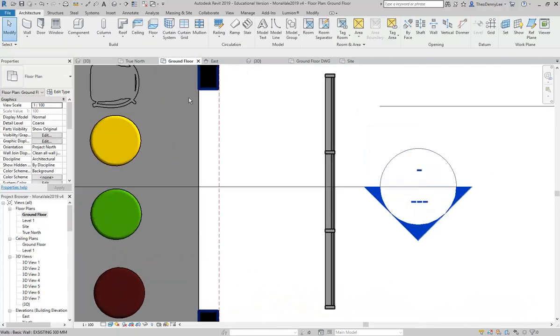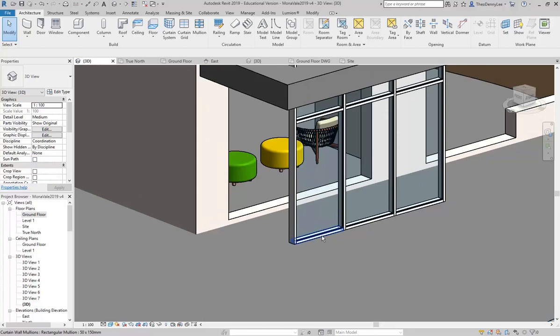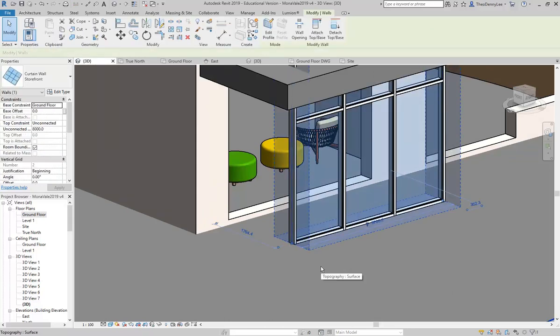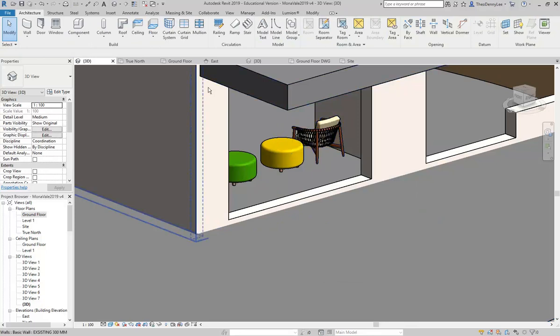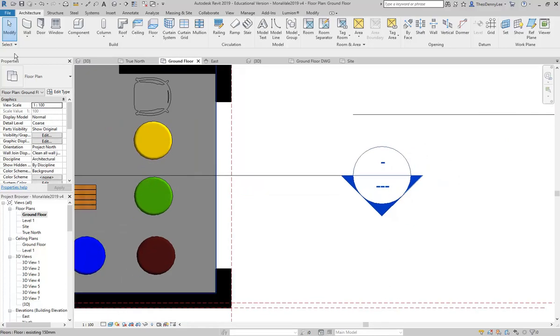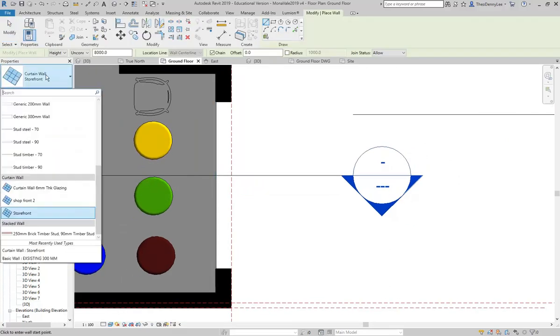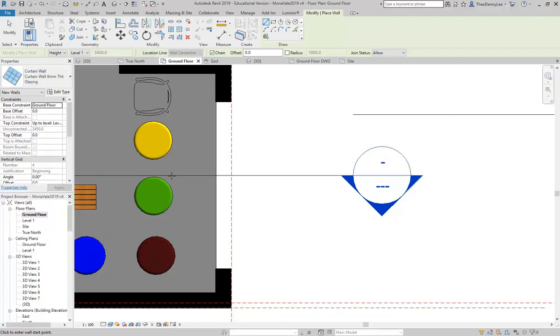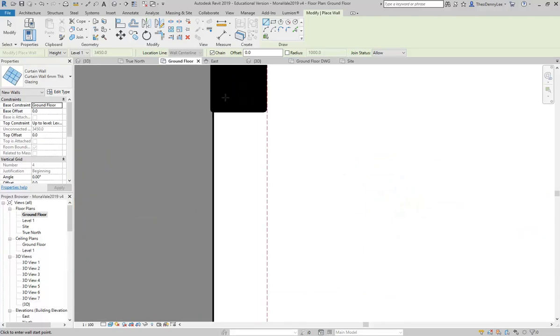And that's fine if you just want to make a quick wall with the framing done automatically. That's handy. But if you want, again, a more plain wall to start, then 6mm thick glazing's the one to use. So again, going back to here, it's curtain wall 6mm thick glazing, and 6mm is the thickness of the glass, and that's normal. So you can see it's got the height just like a regular wall, so you want to leave it on that height option.